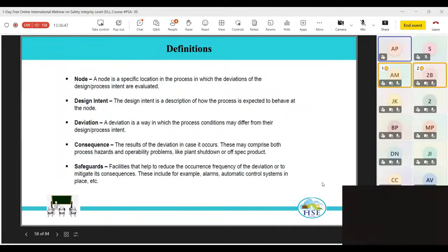Suppose in the P&ID there are some 10 equipments shown and about 20 process pipelines, and we are seeing from left to right, then we would restrict the node to maybe 3 or 4 of the 10 equipments, mark it with a colored highlighter, and segment that particular part and mark it up so that people will be able to identify that node with some number, node 1, node 2, node 3, whatever it is.